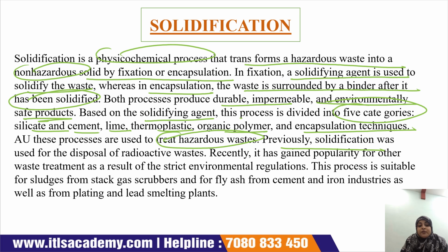Previously solidification was used for the disposal of radioactive wastes. Okay, so previously solidification was used only for radioactive wastes, but now all types of hazardous waste are treated with solidification, and it has gained popularity for waste treatment as a result of strict environmental regulation. This process is also suitable for the sludges from stack gas scrubbers and for fly ash from cement and iron industry, as well as from plating and lead smelting plants.